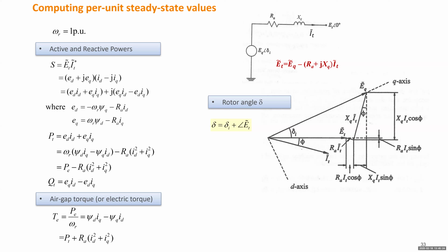We draw it orthogonal to current by turning the direction of current counterclockwise by 90 degrees. So the total will be the voltage drop on this entire branch. Then that will be the Q axis. Later in the Q, we assume the Q axis to be the imaginary axis, and the D axis, which is lagging Q by 90 degrees, will be the real axis, if we use complex numbers.